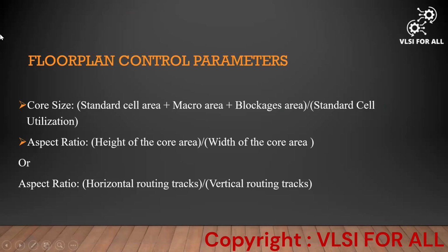And the next one is floor plan control parameters. In the floor plan, what are the parameters it will control? To estimate the core size, we take the standard cell area plus macro area plus blockages area, divided by standard cell utilization. Upon taking all these values, we'll get the core size.